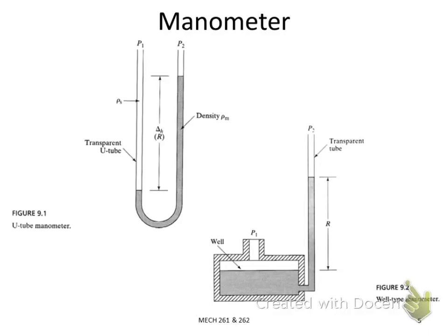So last time we introduced the U-tube manometer. The principle is quite simple, because we have learned that the pressure difference in a fluidic system at two different points is basically P2 minus P1 equal to rho g Δh, where Δh is the height difference on the two columns.